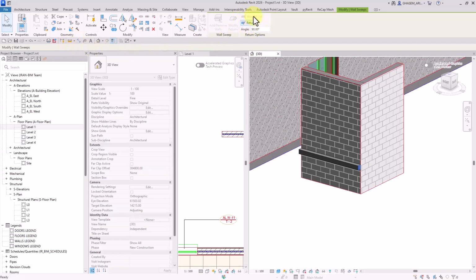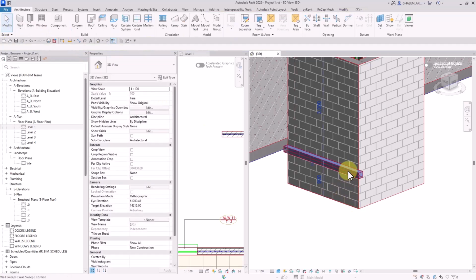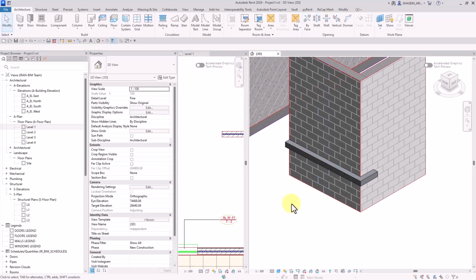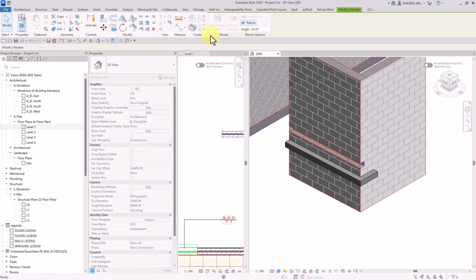Instead, all of them are moved inside the ribbon, using which we can, for example, specify a cut or a specific kind of angle, or we can even stretch this out on a specific course. All right? And guys, the same goes for wall reveal. There's no sub-item in the option bar if we click on modify returns. Okay? All right, let's see what else.